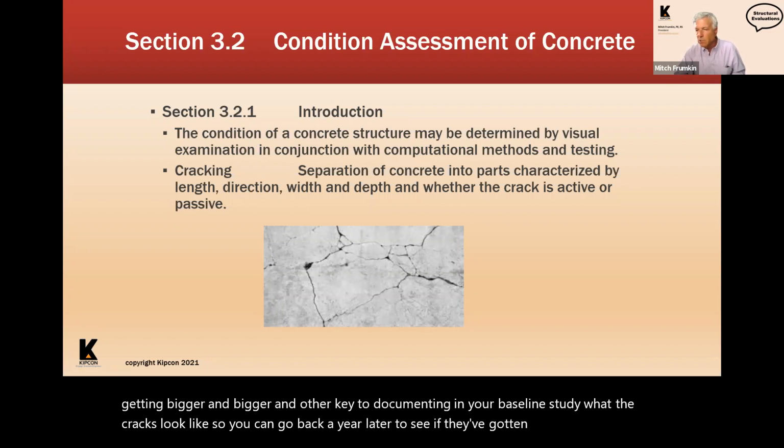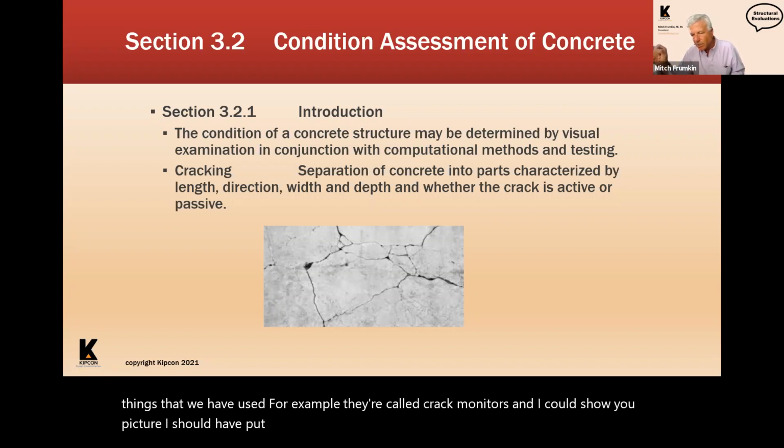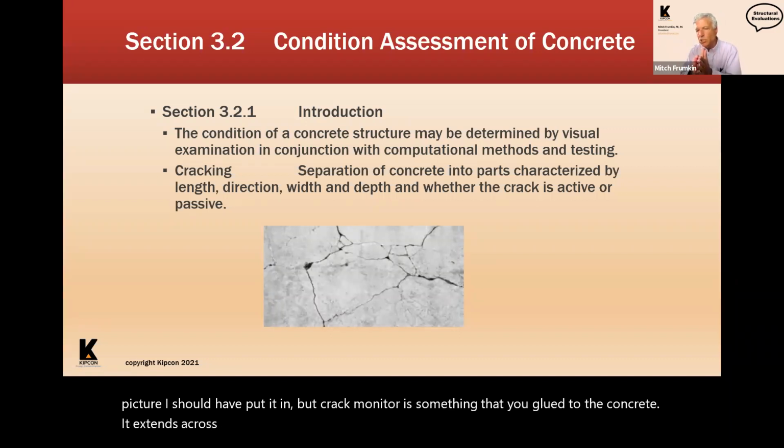There are also things that we have used. For example, they're called crack monitors. I could show you a picture, I should have put it in, but a crack monitor is something that you glue to the concrete, it extends across the crack, and it measures it. So you can go back 6 months later and see if the crack has gotten wider.